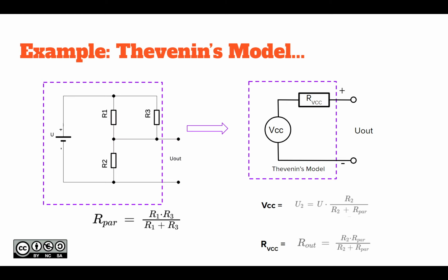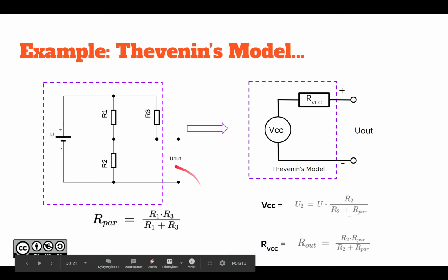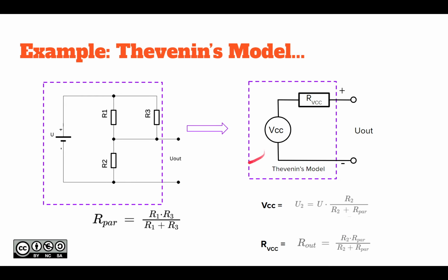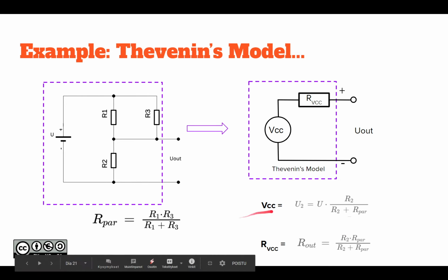So now we have done the Thevenin's model for the system by those shortcuts, using just the series connection of resistors and voltage divider, current, and then the parallel resistors or the current divider. Very simple operations, and then our Thevenin's model for this circuit is there.